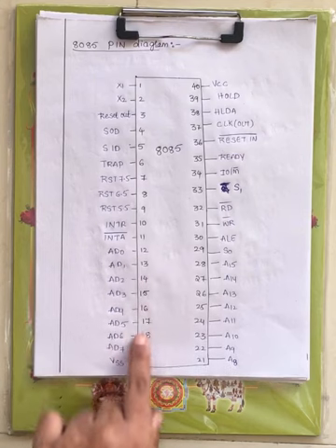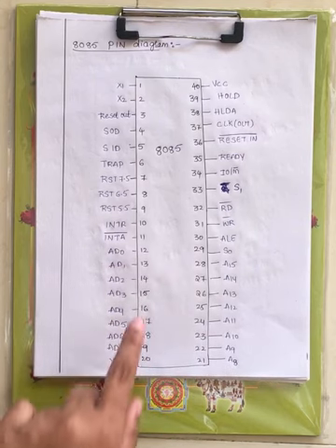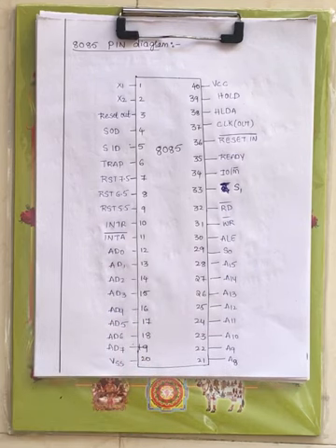Starting from the 12th pin to the 19th pin, you have AD0 to AD7. Now what is meant by AD0 to AD7? As I have said, bus is used to transfer the information between the memory and the microprocessor, or the processor to the input or output device, right?